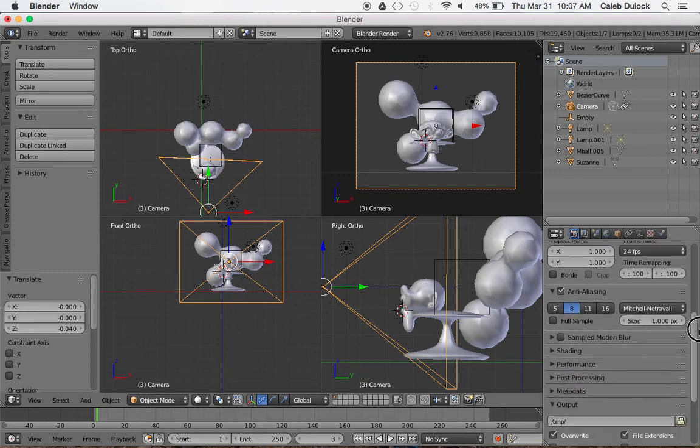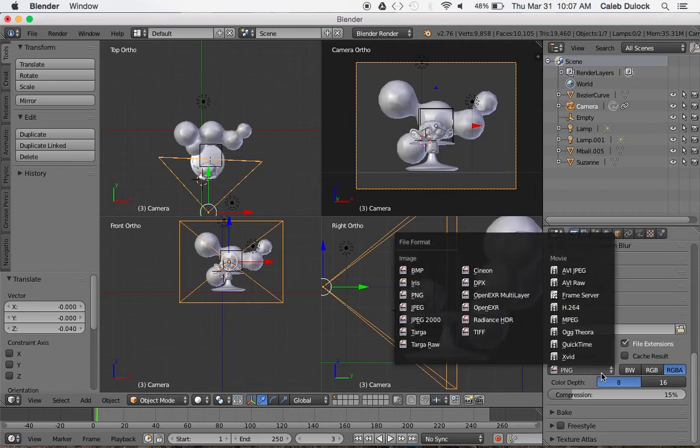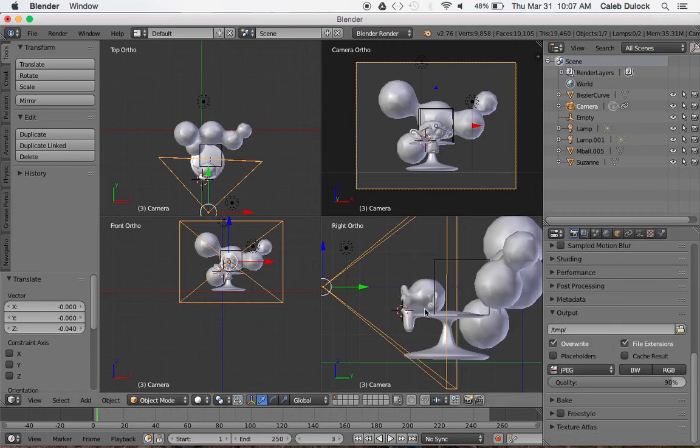And then I'm going to slide down on the settings and go to output. Now down in output, we need to switch this file format from PNG to JPEG, depending on what your system is already set to, but it should be set for JPEG. Highlight RGB and set the quality slider to 100%. Okay, now what we're going to do is go back into our camera properties for the video camera, and we're just going to zoom back in a little because I got a big border here.